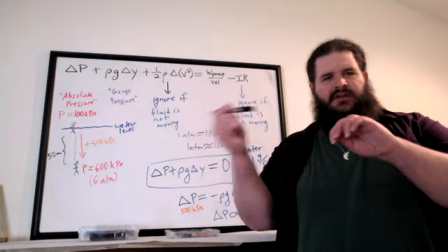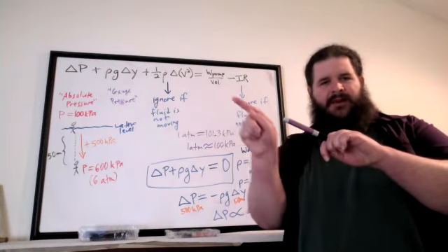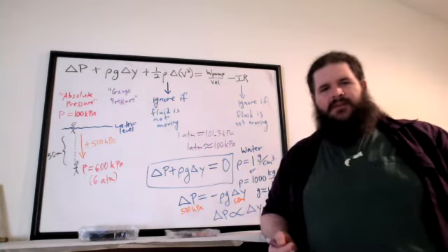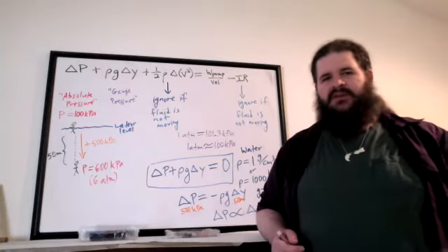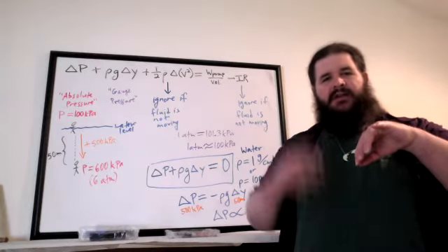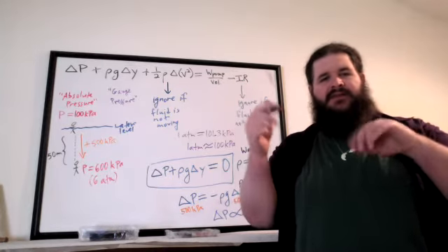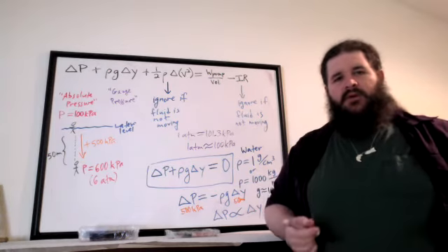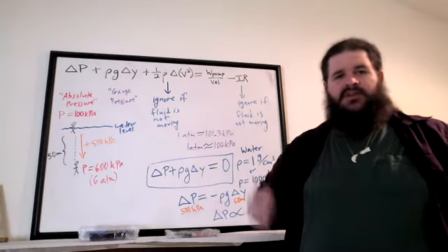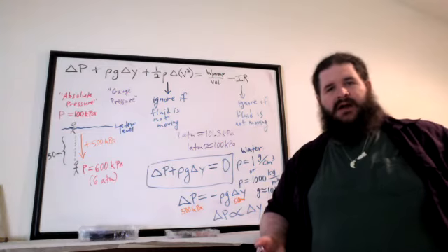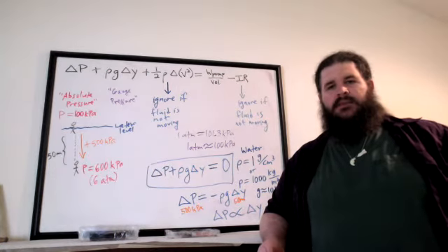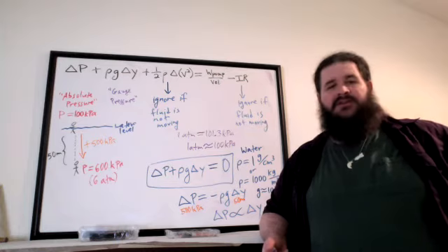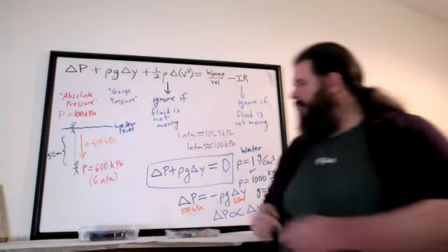Like just this cylinder that you plug into the tire and a stick pops out of it? The reason that stick pops out is because of a difference in pressure. You've got the high pressure inside the tire and lower pressure outside the tire. That difference in pressure makes the stick pop out. And the more different the pressures are, the more the stick pops out, and therefore you see a higher difference in pressure. But gauge pressure doesn't represent what the pressure actually is. Gauge pressure is how different the pressure is from the atmosphere.